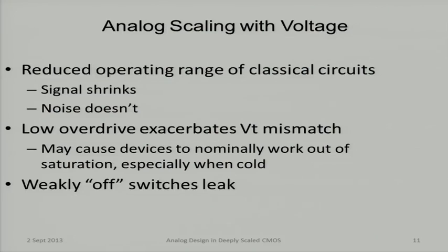Finally, weakly off switches. As I say, I've spent my whole career at Intel designing analog circuits in parallel with the process development. And one of the things that has helped me keep my sanity is to build options into the circuits so that if you're expecting the process to be over here and it ends up over there, well, if you've got some options built in, you can try and move it back. That invariably involves putting switches in the circuit. And when the switches don't turn off very effectively, that means that they're probably loading down some critical node in some way you really would rather they didn't.